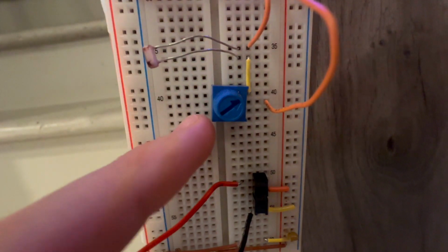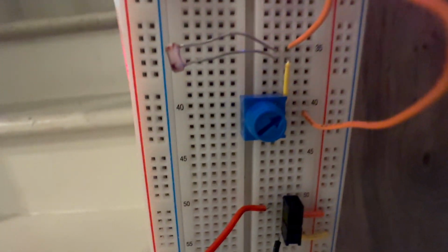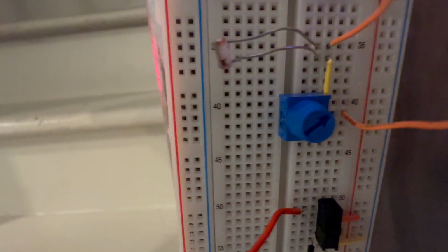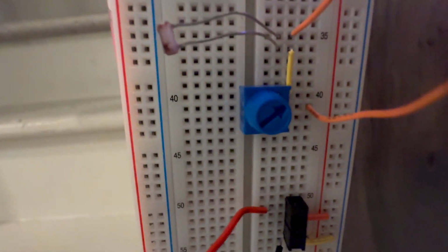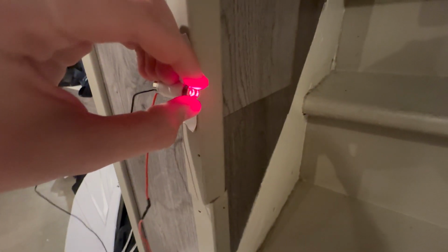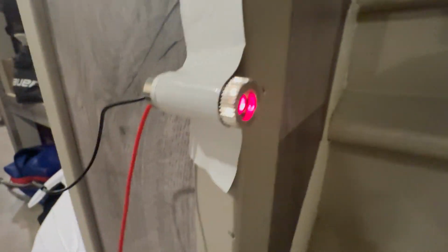With this potentiometer, you can choose how high the threshold is for your laser, meaning that if you're in a darker room, you can set it so that the laser will still work with the LDR. Interesting fact, this specific laser diode actually has a dial where you can change how close the lens is to the diode, meaning that you can change how wide or narrow the beam is, depending on how long the threshold is that the laser has to cross.